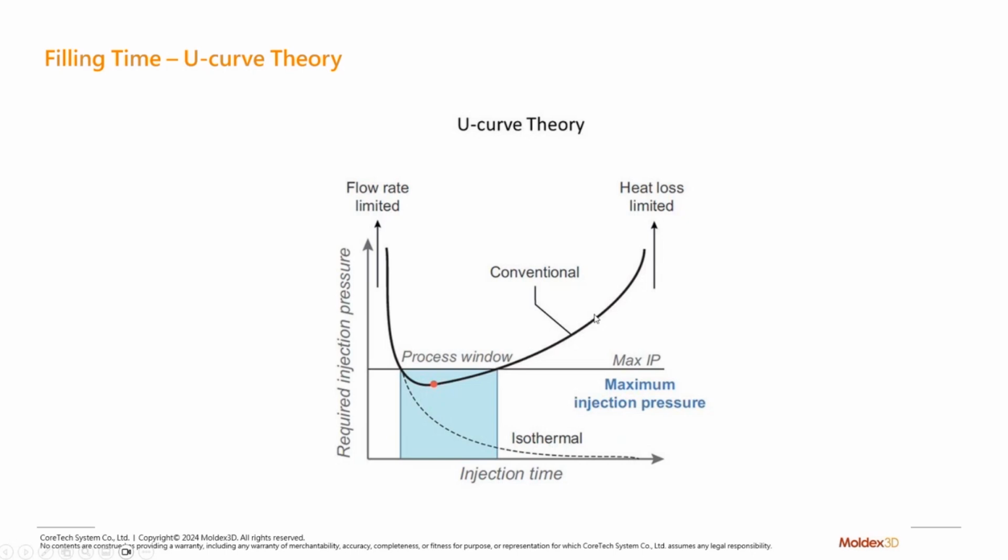Now, it increases again, and this happens because initially there is a lot of material being pushed into the cavity in a very small amount of time. So there's a lot of back pressure, a pushback from the material. That's why the pressure requirements are on the higher side.